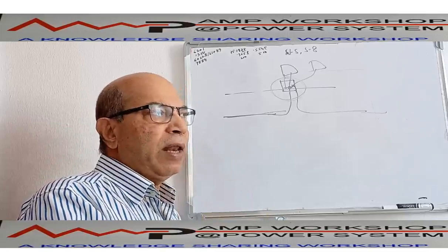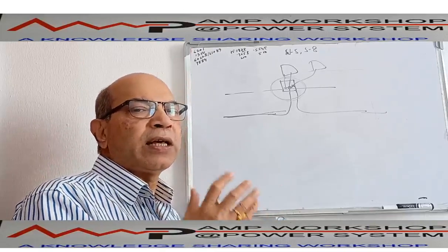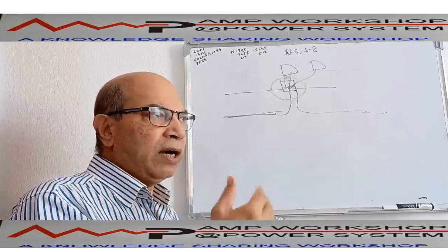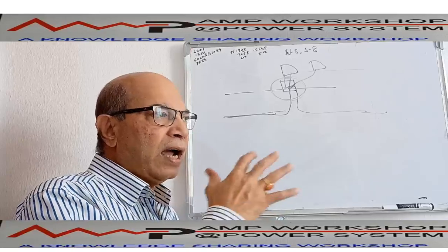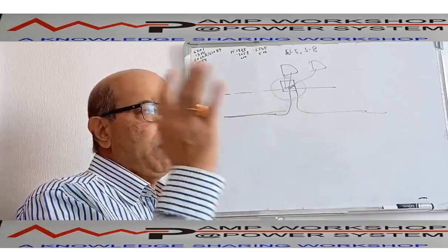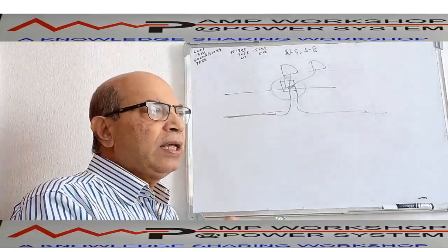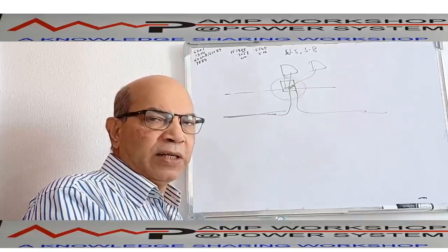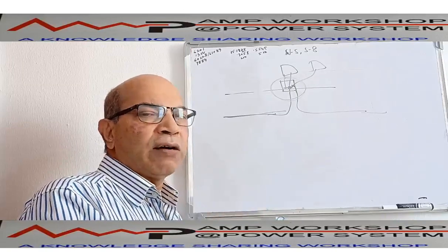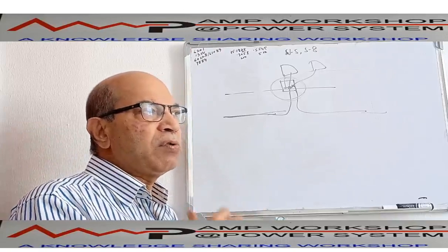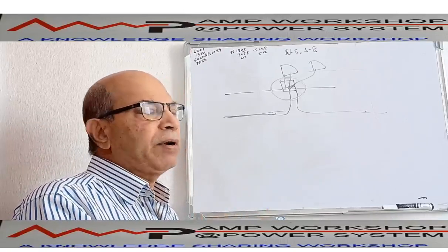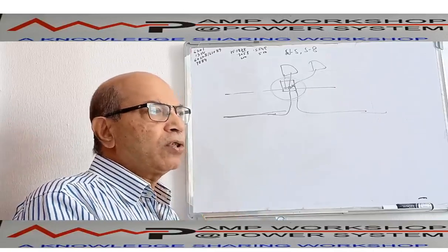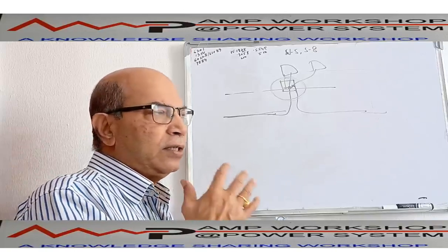In the medium voltage level and in plant electricity distribution, we mainly use the cabling system. We mainly use cabling in the urban area, I mean city, town or suburban area, where high density population is living continually. In that area, overhead conductor is a safety issue, and the power carrying capacity limitation is there. In that case, we use the underground system. So you can see the underground system mainly in urban and suburban areas, but in rural electrification and high voltage transmission and distribution systems, in most cases we use overhead conductors. So that is the best conductor.